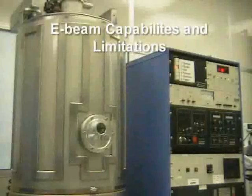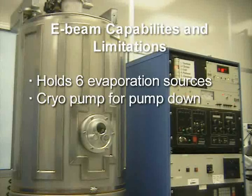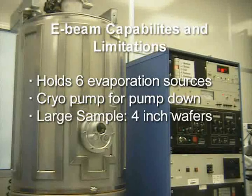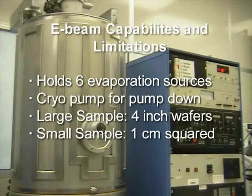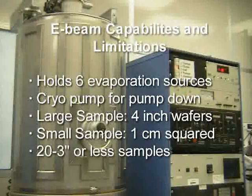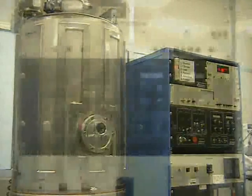The E-beam evaporator can hold up to 6 different evaporation sources. A cryopump is used for rapid pump down. The E-beam can process samples in size from 4-inch wafers to less than 1 centimeter squared samples using the process plate. It can also process 23-inch or less samples using the process dome. It is also to be noted that the backside heater is disabled.